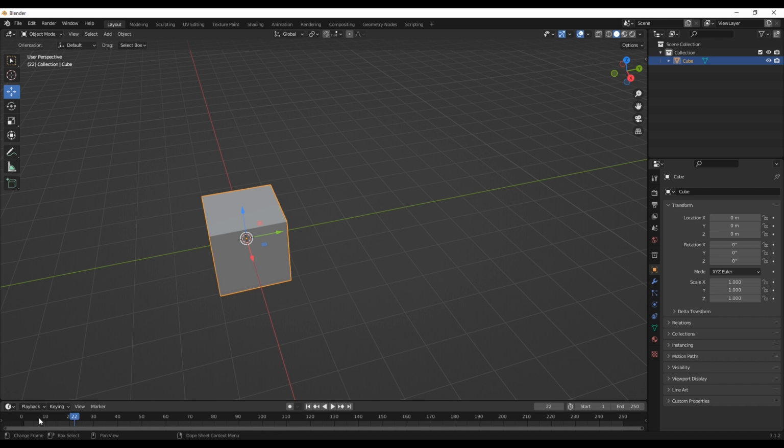So if you look down here, this is our timeline. And this is where you can find your frames. So our timeline currently consists of 250 frames, and you can increase this by just clicking and dragging. And this indicates the particular frame we are currently working on. So if I move, you see that number gradually changes. And now if I stop here, we're on frame 110. So this is our sequence of frames, which would then be converted to time when we're ready to encode a video.